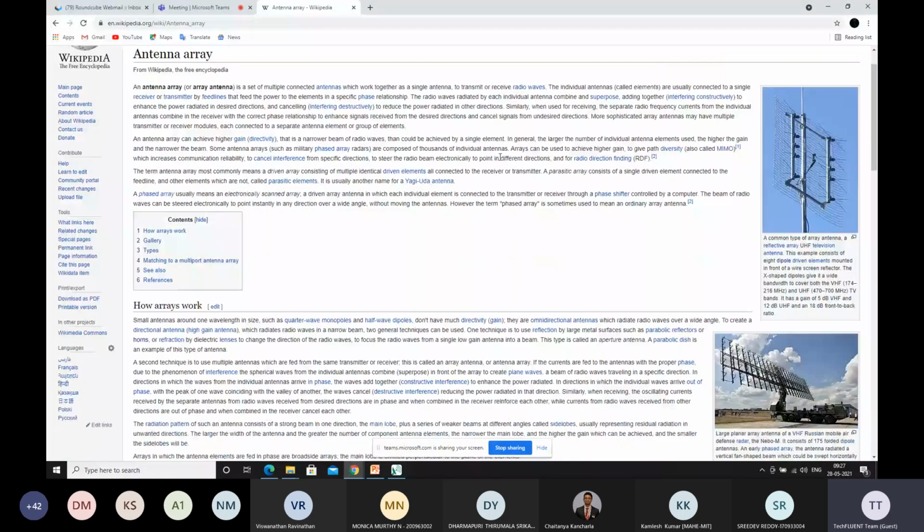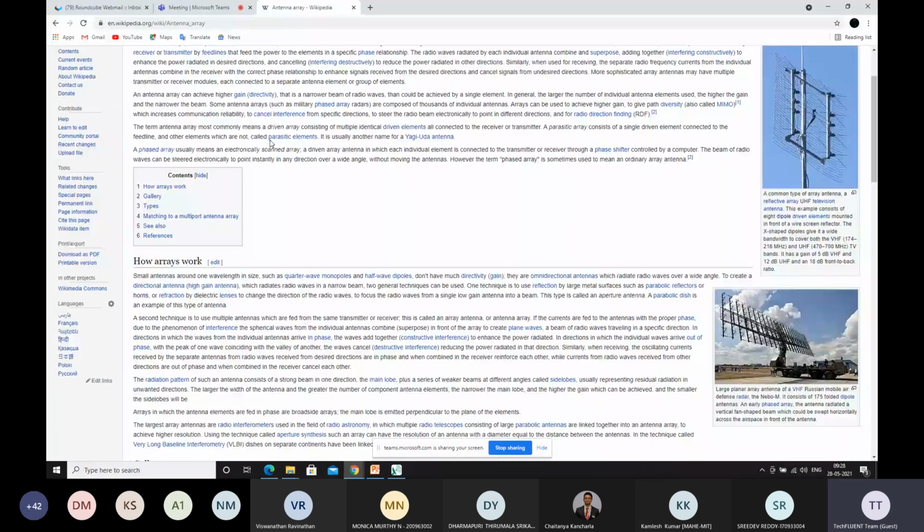the concept of antenna arrays is nothing but increasing the gain and throughput through the constructive adding nature of your antenna. So constructively, your radiation beams will increase in all the directions, and you'll be getting an added up gain in both the directions. With dipole antennas, the concept of the Yagi-Uda antenna is also a dipole array only. So it's like a dipole array itself.